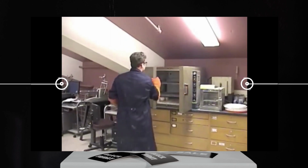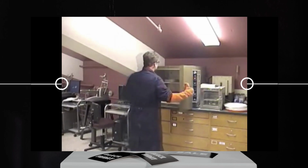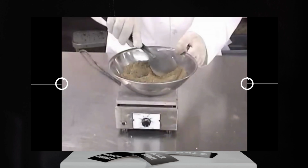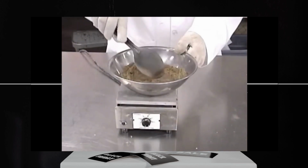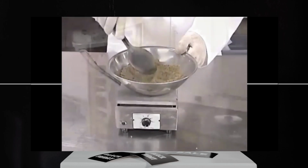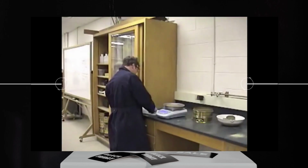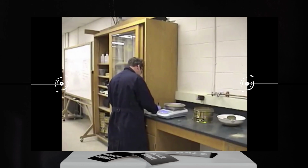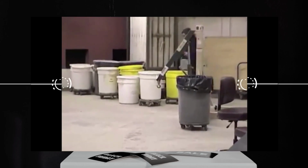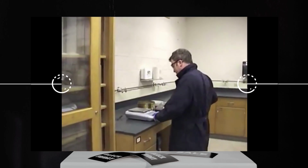Dry the sample by heat. Avoid overheating, scorching, or any other alteration of the aggregate particles during the drying process. If a hot plate is used, stir the sample uniformly, ensuring that no sample is lost during the stirring process. Make successive readings to ensure that the sample has dried sufficiently. The sample is dried sufficiently when we have less than 0.1% loss in successive readings. We now want to allow the sample to cool and record the mass to the nearest 0.1 gram.